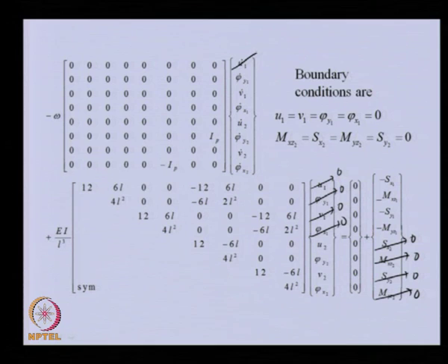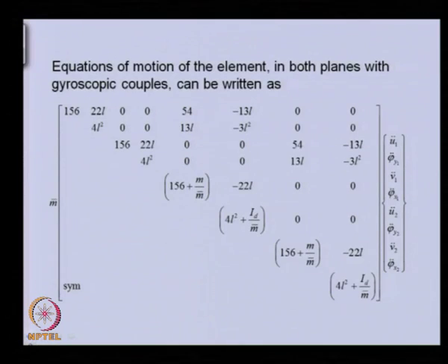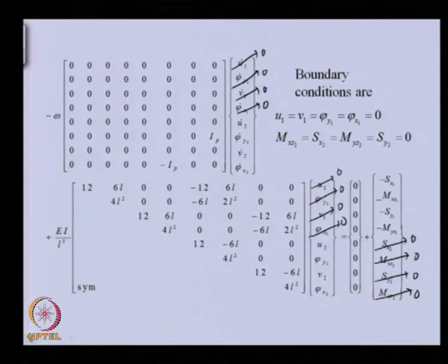Similarly, we can equate the velocity terms at node 1 to 0. Even for the mass matrix, we will be having these as 0. Now, you can see that in the right hand side only the last 4 rows are having 0 values. These are unknowns. So, we need to eliminate them from the final reduced form of the equation.